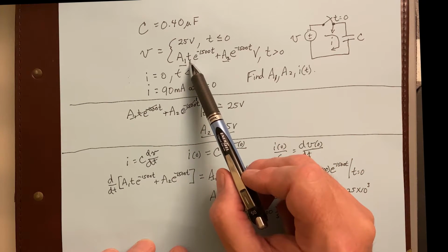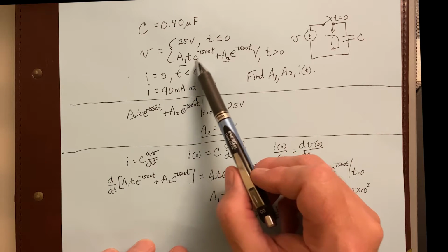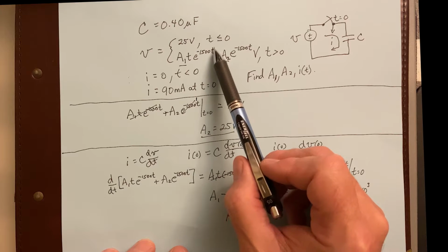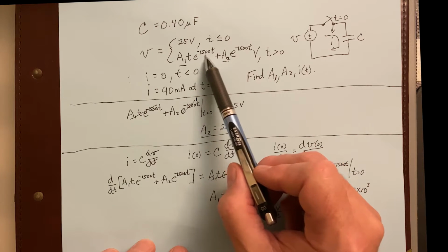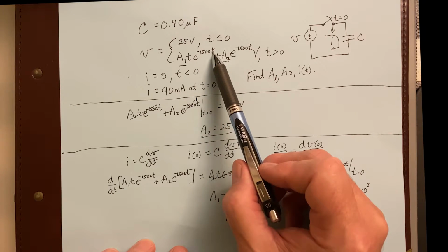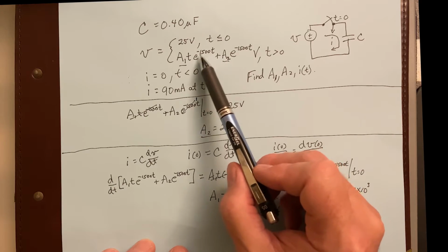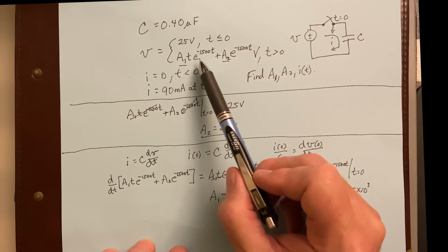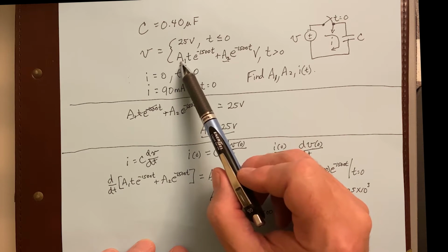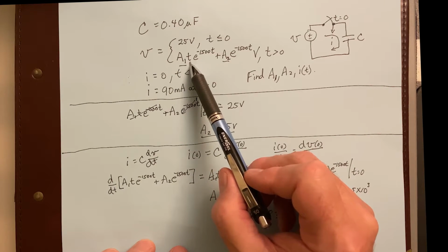But this has a T in there, and T is going to be in seconds. There is no unit attached to the exponential. T is going to be in seconds, and these 1500s, even though it doesn't say so, have units of radians per second. So radians per second multiplied by a second is just going to be radians, which is unitless. So there's no unit attached to the exponential in both of these. The units come about because of the coefficient and that T right there.